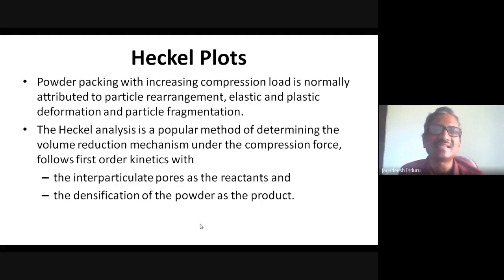This rearrangement will occur even in the tapped density also. First you do a bulk density, where you just add a powder into the measuring cylinder, but in the tapped density you hit it onto a hard surface repeatedly till the value is constant, because you are allowing particle rearrangement.